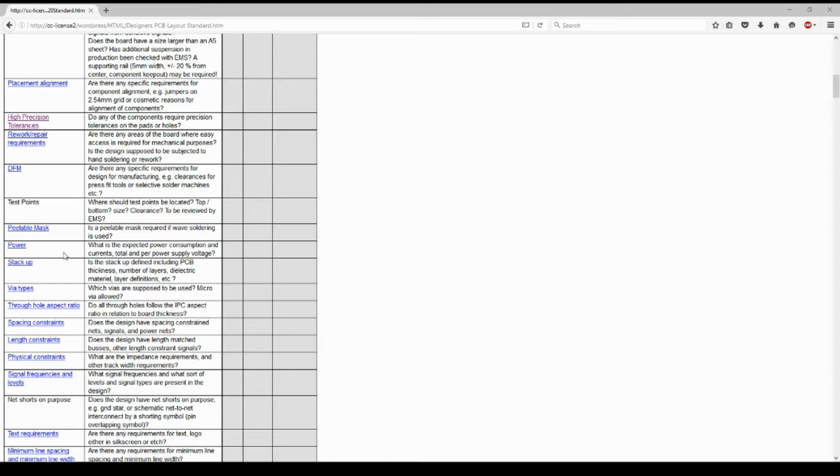Sometimes it's much better to have them at the top, so when you are in the lab you can access them from the front rather than turning the board upside down. Again, if it is part of production that these should be used, then it's important that the EMS has verified those locations.